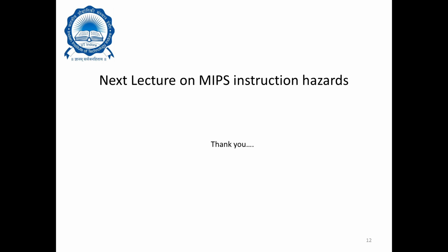Okay, so we are done with this lecture, and in this lecture you would have learned several things about the MIPS Datapath, starting from the overall connectivity, the interconnectivity of each of the blocks, how to calculate the jump target address, how to calculate the branching target address, how to do that using hardware. Okay, what are the major control signals, what is the role of the different switches. You've learned about 5 different switches or multiplexers here. Okay, you've learned about the centralized control unit and a sub controller known as ALU control. Okay, so everything you have seen, and what are the bit field sizes. So in this lecture we have pretty much covered the MIPS Datapath.